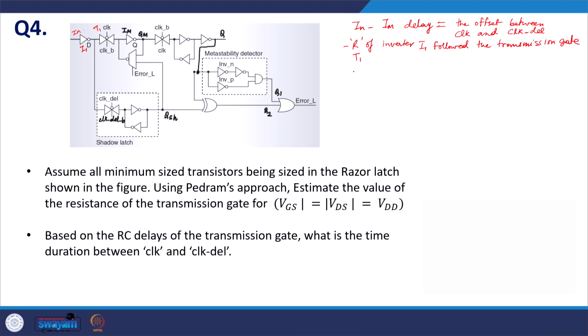For that, we first calculate the voltage of node X. How do we do that? Suppose this is discharging, the value of node X would be sufficiently high such that it is much larger than the thermal voltage. So, all the transistors would be operating in subthreshold saturation.